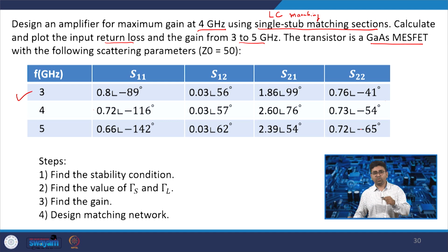So, if you want to design the amplifier at microwave frequency, you should know the S parameters prior to doing the design. You can either use a simulator, which will also provide you the S parameters, or if you are using a specific transistor like GaAs or GaN, you will get them from the foundry.